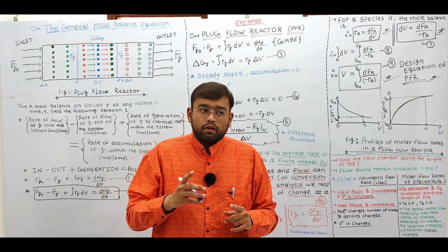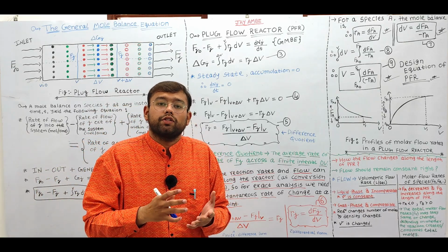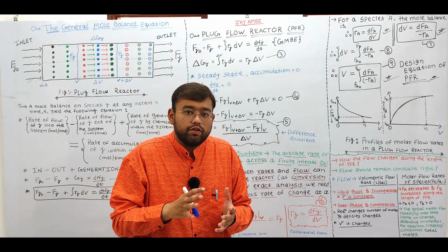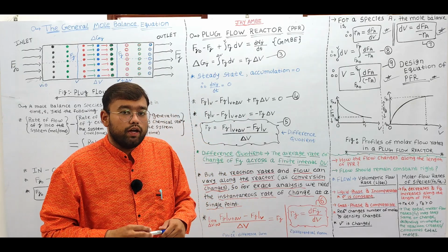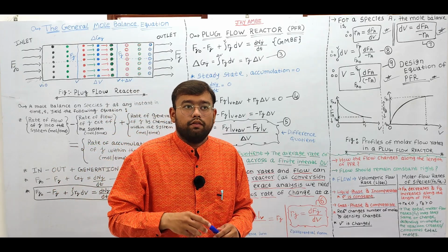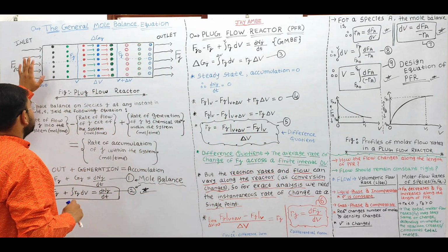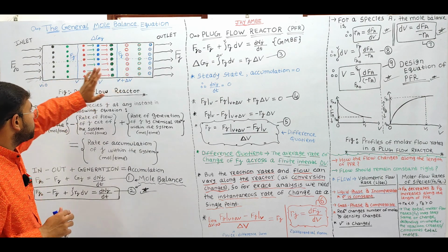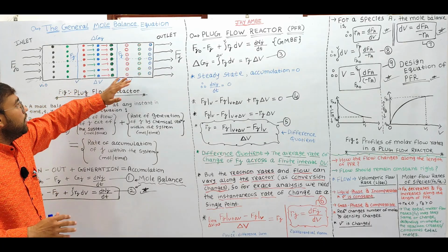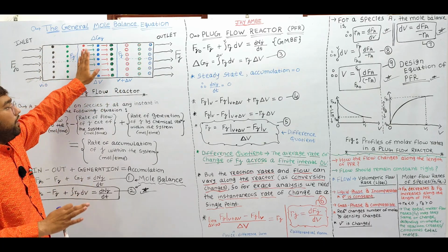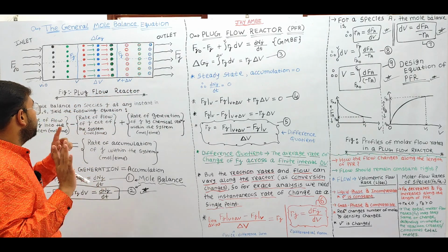Let's take water. We cannot compress water by applying pressure and temperature; up to significant pressure and temperature, water cannot be compressed, so it is called an incompressible fluid. So with a liquid phase reaction and incompressible fluids, during the progress of the reaction, with respect to time, length and volume of the reactor, the density of the liquid will remain the same. For that reason, the volumetric flow rate will also remain the same.